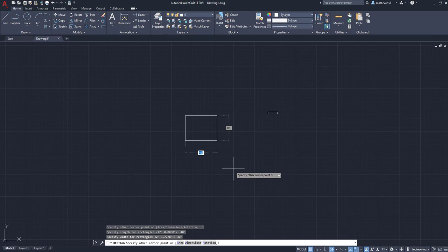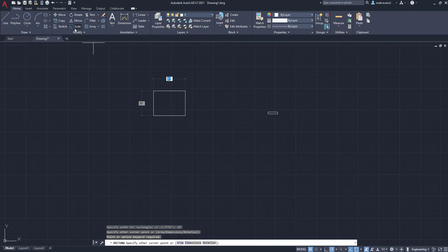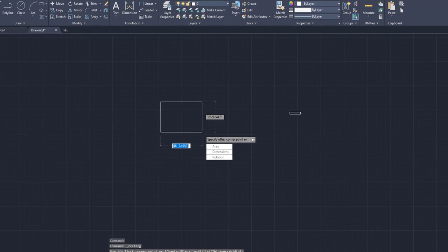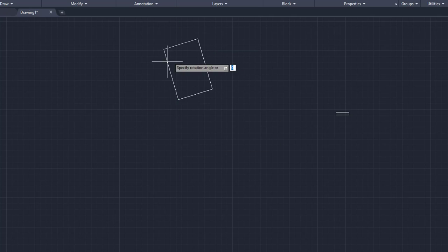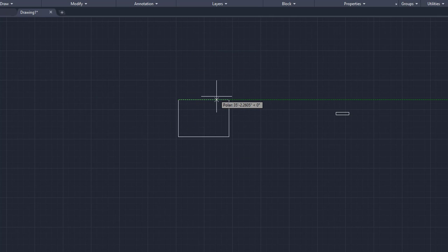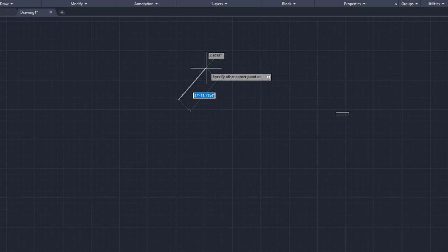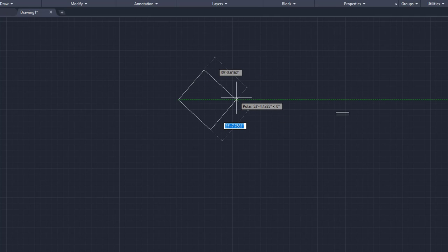So the last and final thing you can do is we're going to go up here to rectangle again, and we're going to give the down arrow, and this last input allows you to rotate right here, this rectangle, wherever you want to. So we'll rotate it like that, and then you have, again, 35 feet, and we'll tab over to the other dimension, to 40, and there you go. You have a rectangle that's in that rotated position, 35 by 40 feet.